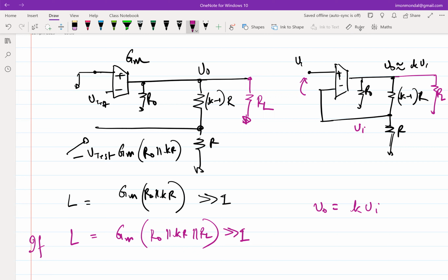If you need to make a good amplifier, by definition it should have high gain, or some gain, but more importantly, that gain should be independent of what it is driving. A good voltage controlled voltage source, if we have to be even more specific. And that is possible in this case because you have negative feedback.